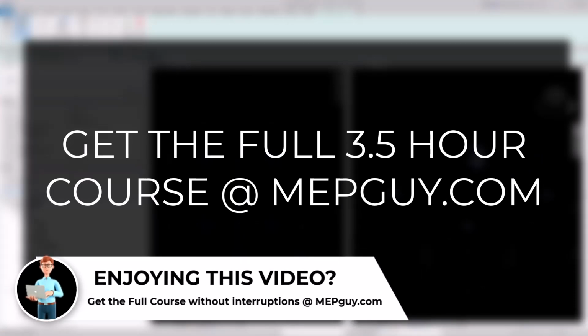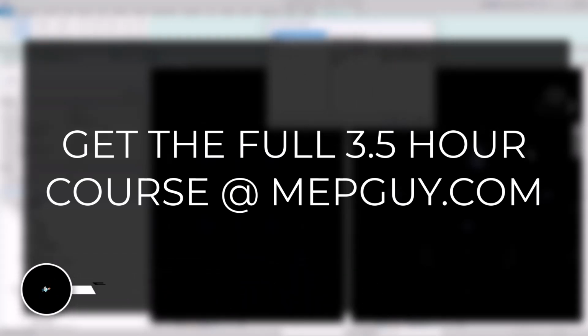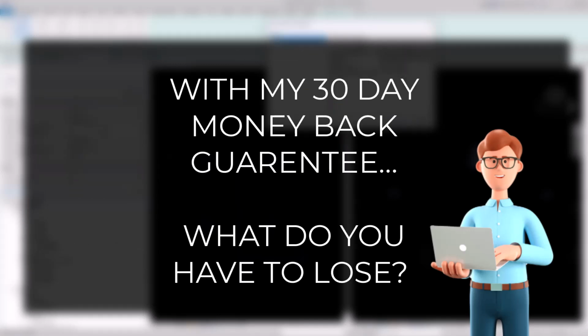Let's click on that. Now we can see that there's some settings associated. We have a main and we have a branch. So our main is this duct right here, and then our branches are the ones in green. So the main's in blue and the branches are in green. So maybe we want to put our main up to 10 feet. Okay, and then we'll click on our branch, and maybe we want our branch to be 10 feet as well.